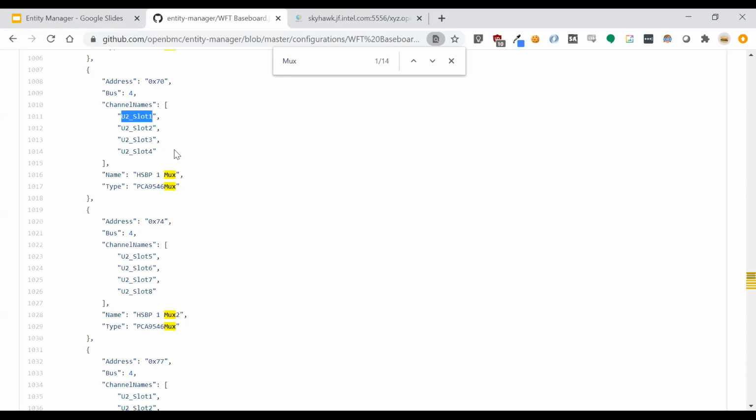Does it support runtime configuration change? Yeah, it does, and it just depends on how you want to retrigger it. Like I said, right now, if you DC cycle your system, it will detect anything that changed. Or there's a rescan method on D-Bus that the power supply sensor and DOS sensor use to trigger a rescan mid-flight to add or remove configurations for power supplies. So that's an option, or you can just write a script to rescan whenever you feel like it and call that method.